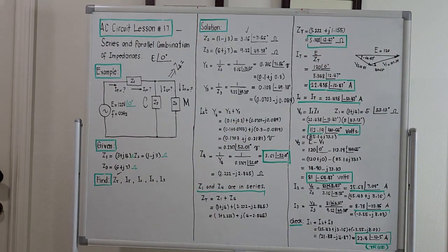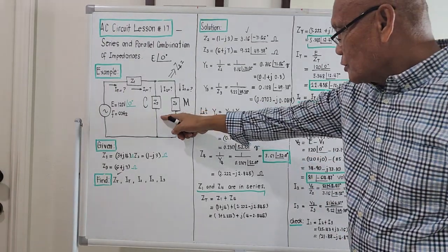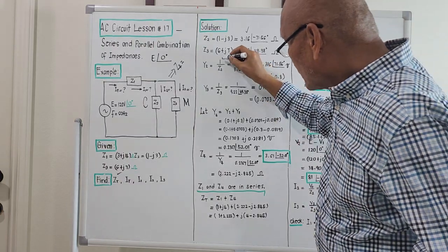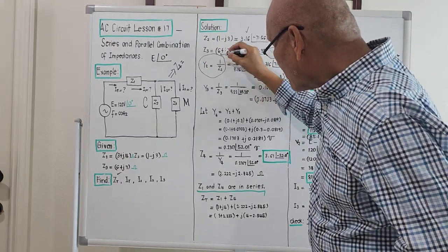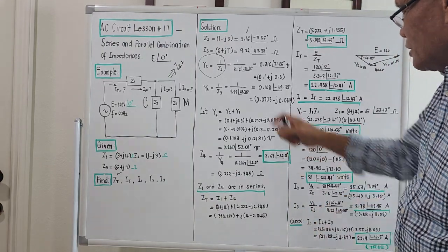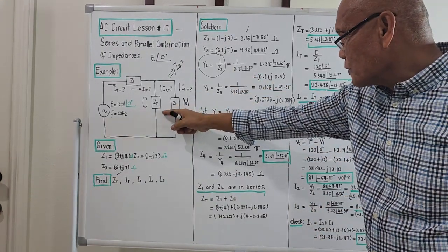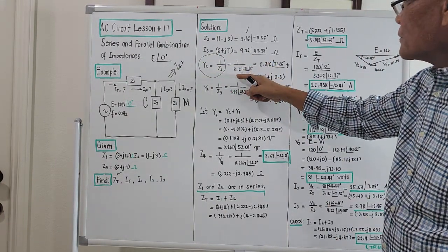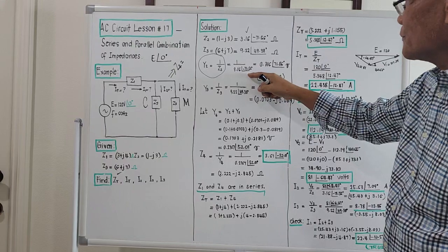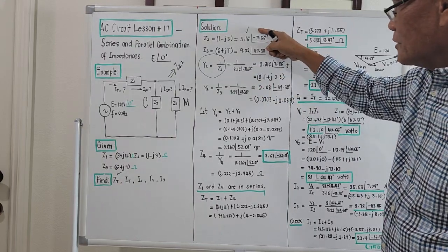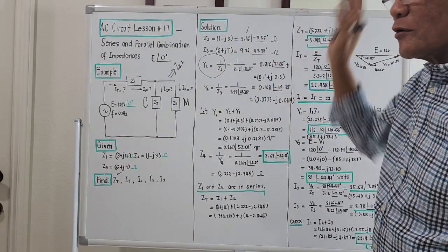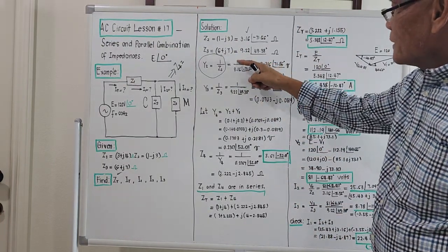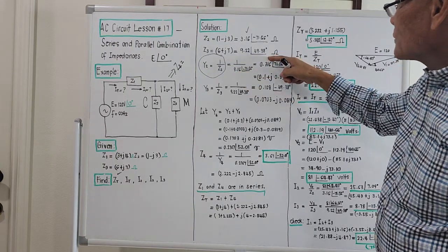Let's try to compute for, we now know C2 and C3 in polar, right? And by definition, admittance is actually the reciprocal of impedance, right? So if we know C2, we could compute for the Y2 of this one. So Y2 will be 1 over C2. This should be 1 over 3.16, angle negative 71.56 degrees. Take note of the sign. You just made one sign wrong, it's all wrong. Okay? Negative 71.56 degrees. 1 divided by 3.16 will be 0.316.